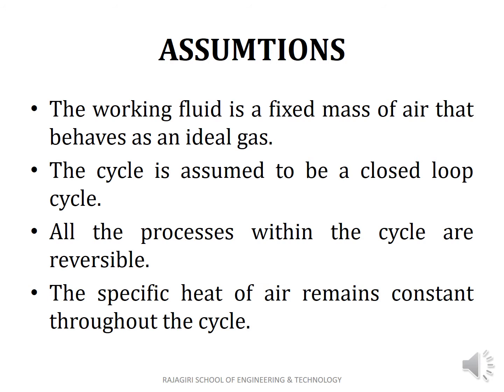Like every other cycle, here also we make some assumptions to simplify the analysis of the cycle. The first assumption is that the working fluid is a fixed mass of air that behaves as an ideal gas. This is why it is also called air cycle refrigeration. The cycle is assumed to be a closed loop cycle. That is the second assumption. And the third one is that all the processes within the cycle are reversible. There is no irreversibility. And the last assumption is that the specific heat of air remains constant throughout the cycle. There is no variation of specific heat with temperature.